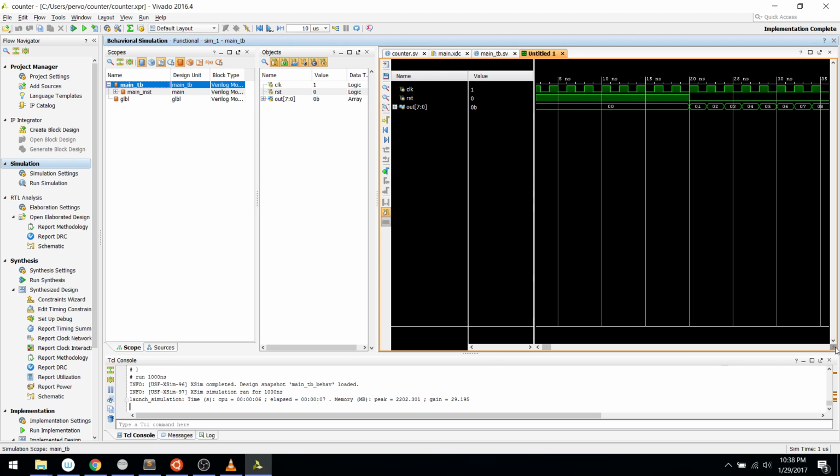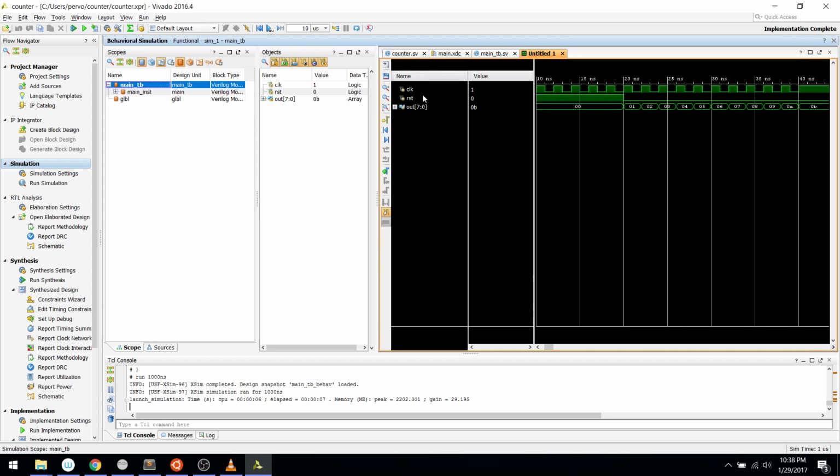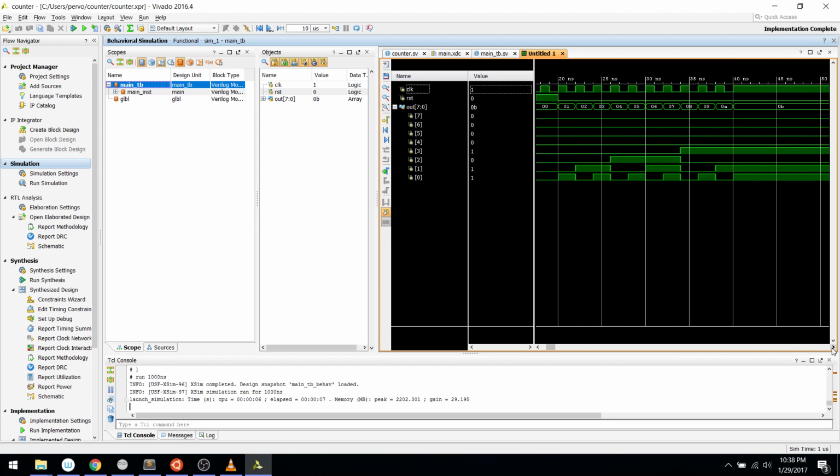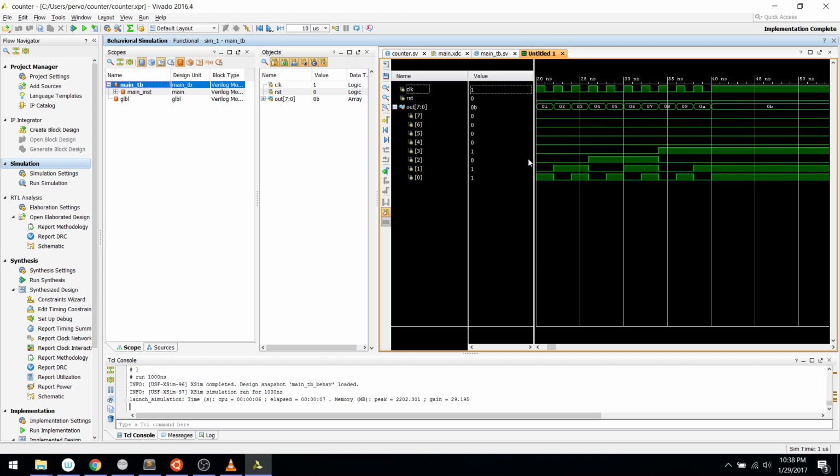And then we deassert reset, and continue cycling for 10 cycles. And you can see this register goes through 10 values and then holds its final value because we stopped clocking it. And if you want to look at the individual bits, you can see the typical periodic pattern of the bits of a counter.